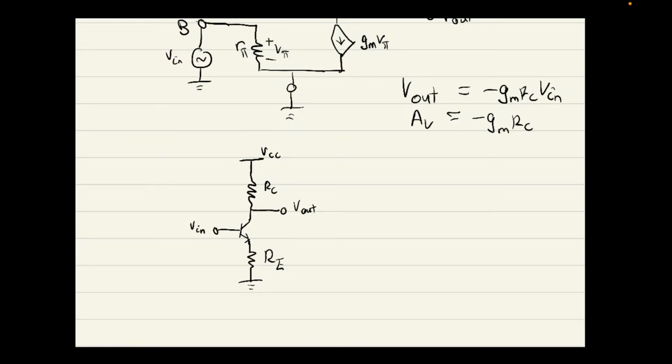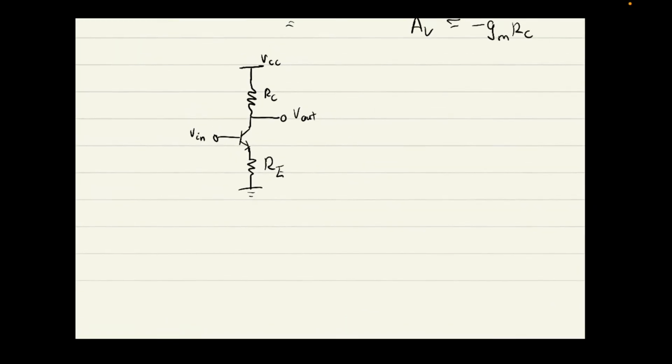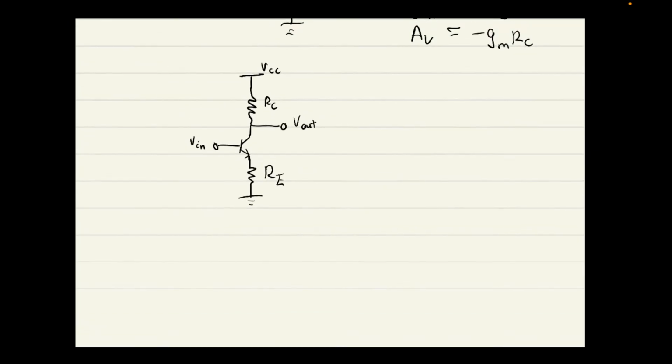So this resistor over here, attached to the emitter, is called a degeneration resistor. It introduces negative feedback. You don't need to know exactly how it does that, but it stabilizes your gain, and also makes it a bit less dependent on gm and more dependent on your circuit parameters. I'll go over feedback in a couple of sections. So let's derive the gain equation for this.